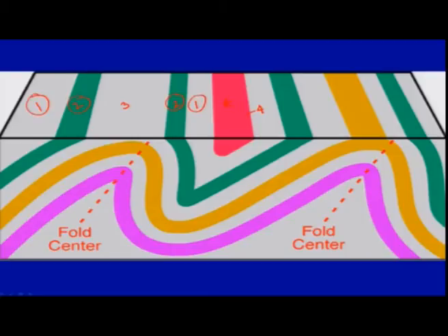That is again an important part which you can make out, and also that this white layer, that is the 3, is comparatively wider than the others. This is because it is the top of the crust, or the crest of the anticline. That is one of the reasons why it is showing the wider space here, because this is an eroded surface. This part we see at the top is a completely eroded one, so we just see the layers which are coming up.